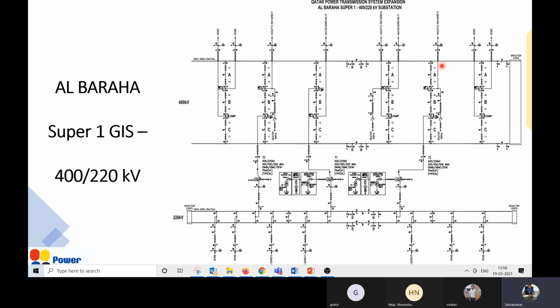In the Ferranti effect case, the temporary overvoltage case, or the load throw off or a fault with load throw off, in all these cases the rise in voltage is well within the class 4 and class 5 rating of surge arrestors. So we can choose either class 4 or class 5 surge arrestors.